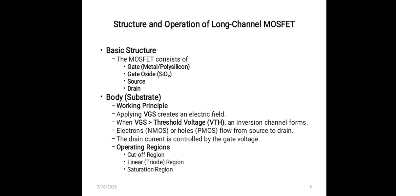Now we will go with the structure and operation of long channel MOSFET. A long channel MOSFET contains 5 major parts, whereas the MIS structure has 3. This long channel MOSFET has 5 parts: one is gate, another one is gate oxide, source, drain, and the body, which is also called the substrate. The gate is separated from the semiconductor by a thin silicon dioxide layer called the oxide layer. This acts as an insulator for the device.